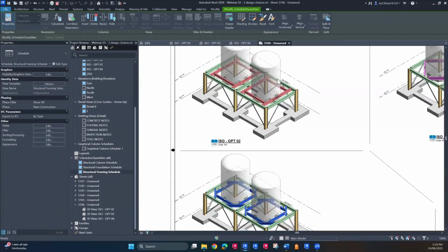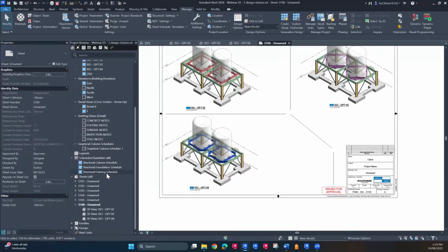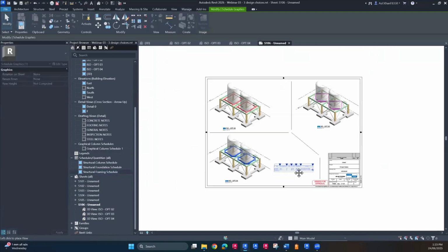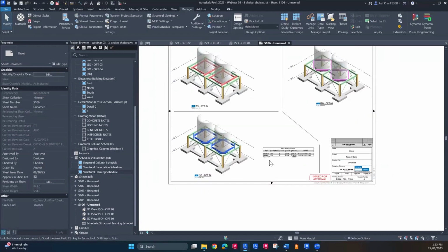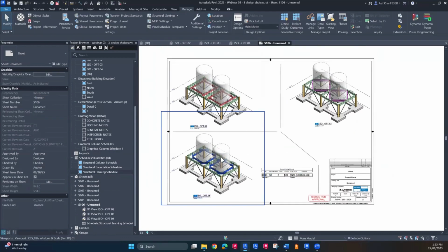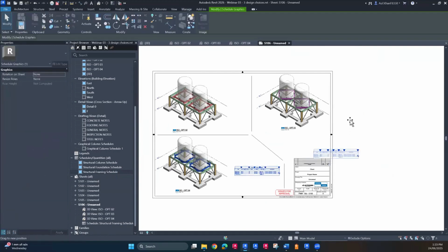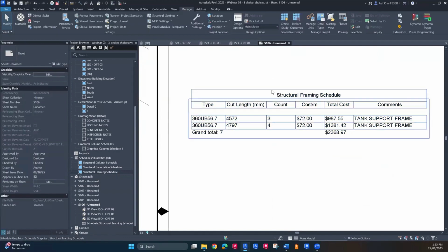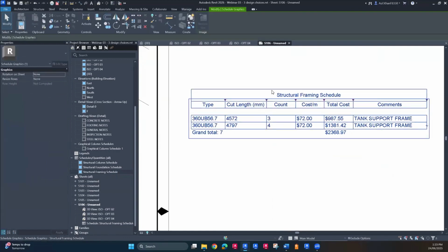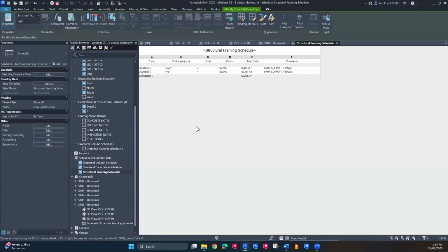All right, now it's time to place this in the design sheet so that we can present our design with some costing. Once I drag and drop it over here, you must be asking yourself which table this is referring to. Is it referring to 1, 2, 3, 4, or is it counting everything in the table? And that's a very good question. In this regard, we have a wonderful system in Revit where you can assign different design options to the table. Now, let me go to the table first. Let me show you where it can be found.